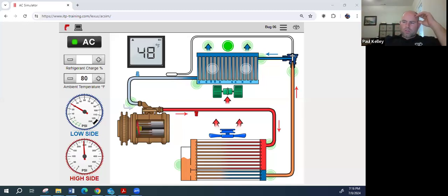And she said she's had to try to defend lemon law buyback cases when all the technician wrote were 3 letters, NPF. So if we rolled out and you felt this and it was like, oh, the AC's cold, NPF, no problem found. Now that wouldn't be the case on this because we know this customer did DIY repairs, but just consider the lesson there. NPF, what could you do better to demonstrate that you actually tried to duplicate the concern or you tried to verify the customer's problem? What would you do on this car?